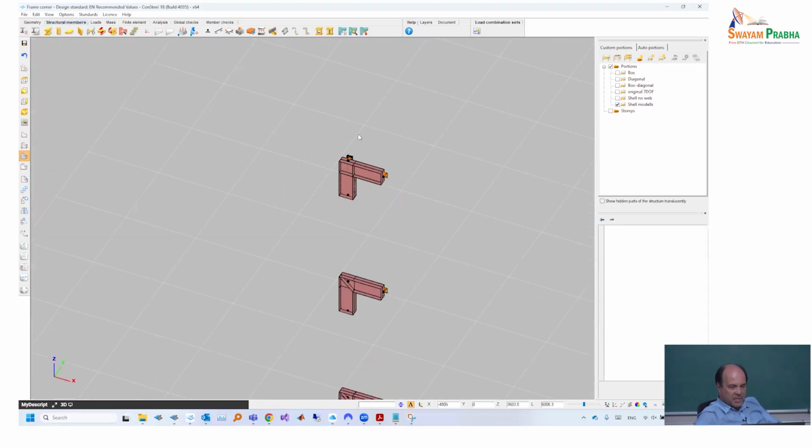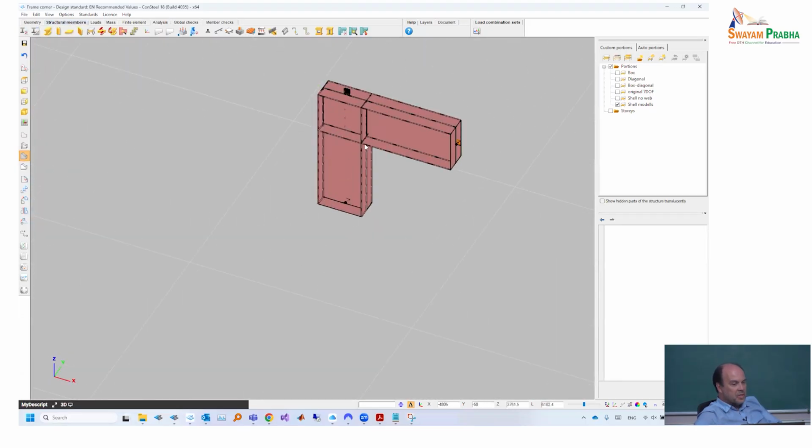Yeah, here is better visible. I used for the first one this sort of box configuration, but it is very often used for metal buildings, that the flanges are continued into the adjacent element, and finally the web panel will be framed by flanges and stiffeners. Of course, some of these plates are stiffeners welded into the one element, others are end plates or the flange of the element. So it doesn't matter, but they are all framed together.